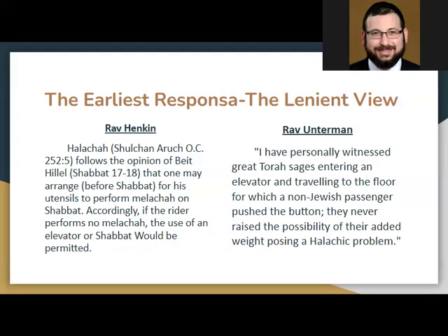So I mentioned, for example, the Bayit and the Shabbos elevator there, and you might think, well, every time you step into an elevator, isn't there like a little motion detector, some kind of a laser that's going across that detects a person there, and that's how it knows if there's somebody in the door, so that the door doesn't close on them. Well, Shabbos elevators will often have that function disabled, and there's an auxiliary system that elevators have where it's not a laser, but there's a sliding part of the door itself that when pushed in stops the door from closing.